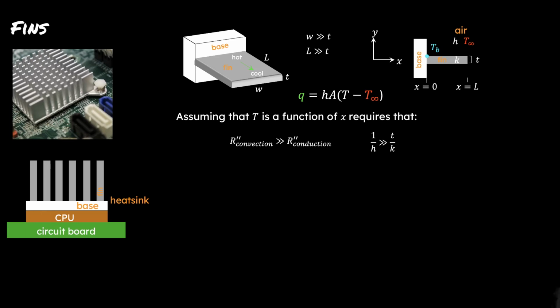Here we are emphasizing conduction in the y dimension along the thickness because most of the heat loss is along the faces of this fin that are defined by L and W. Getting heat to this face that is defined by L and W requires heat transfer in the y dimension along the thickness dimension.